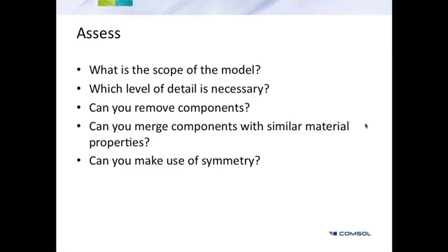You would have a very large mesh for your finite element simulation. But even if you solve it, those details might hide the important features of your analysis. Rather than looking at real effects, you would be looking at effects that you don't have any control over, and you would not realize what you're dealing with. So it's quite important to modify and simplify when dealing with simulation.